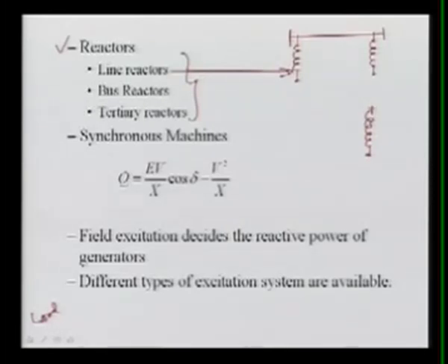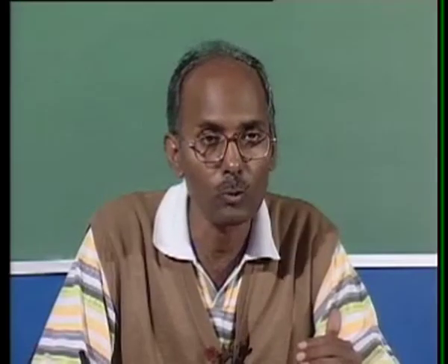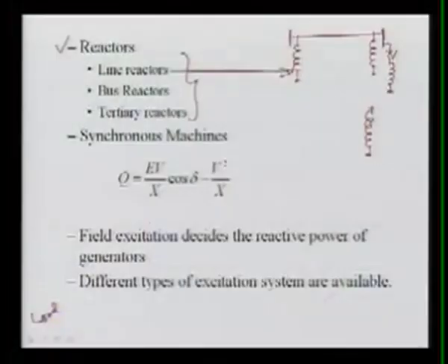Another is your bus reactors. Bus reactors here normally, this is your bus. Here normally we use some switch, and here the bus reactors are there. These bus reactors are not permanently connected, meaning they are normally in the off condition, and whenever they are required we can switch them in, and then we can switch them out when they are not required. So this is your bus reactors.